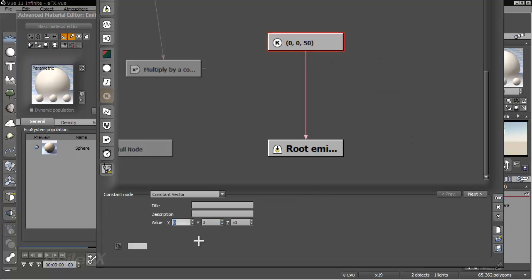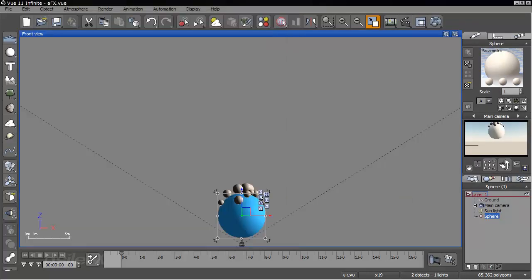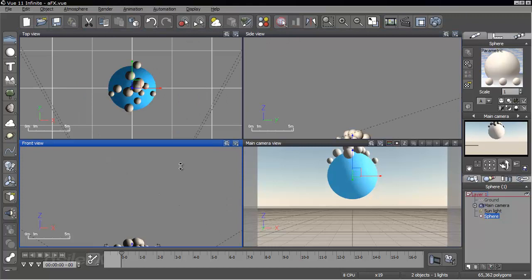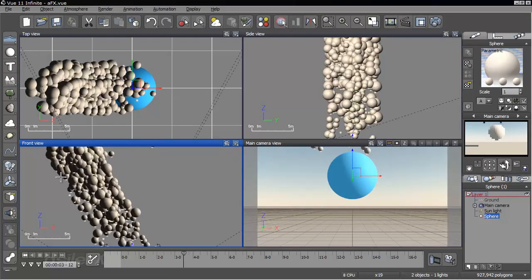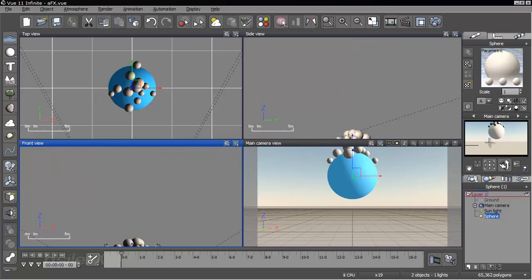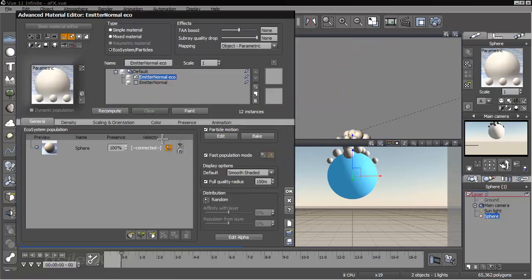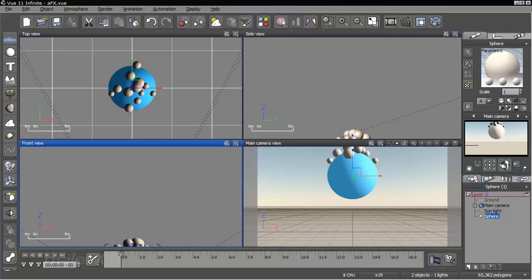So as we change the directions and intensity on the velocity, now we can see it moving to the negative x, because I added a negative value. So it's all based on direction. And I'm just going to go ahead and disconnect this. You can right-click on that drive with a function button to disconnect it and go back to the default.